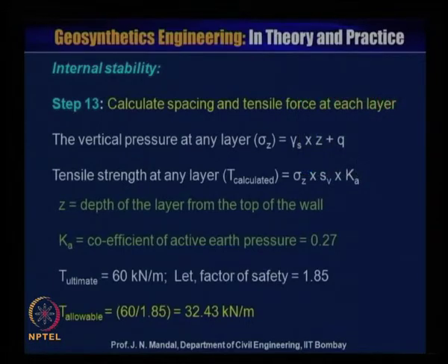So we have covered the external stability. Now I will address the internal stability, that is step 13. You have to calculate the spacing and the tensile force at each layer.